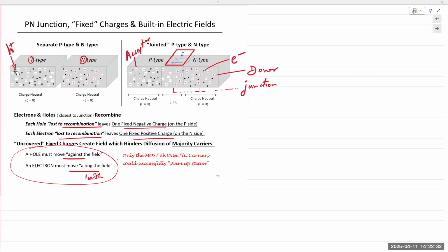It doesn't matter what doping level it is, how many atoms we're introducing, light doping, heavy doping, it always ends up diffusing to a certain extent and then being blocked. What it's trying to do is diffuse into the material until the point where the charge is electrically neutral, or the device overall is electrically neutral.